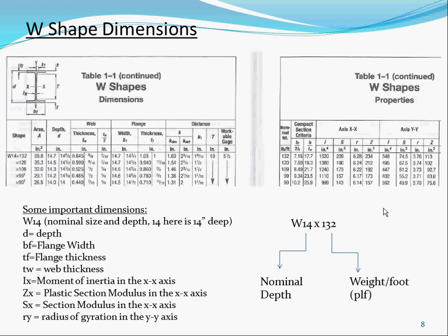However, obviously, the deeper the section, the better capacity you get and the lighter it is, but you might not be able to fit the column or fit the beam. So those are some of the design concerns as well.